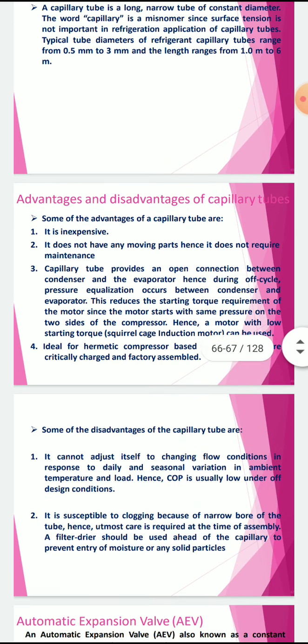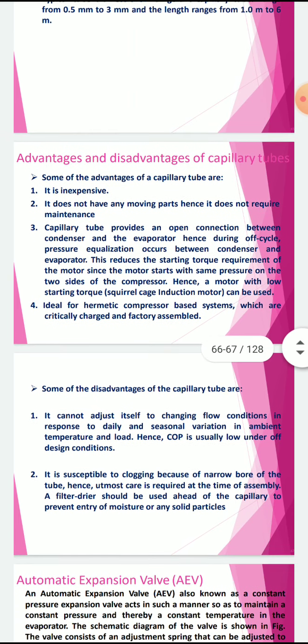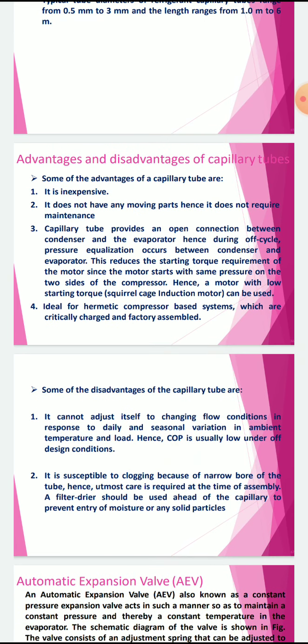Advantages and disadvantages of capillary tube. Some of the advantages of capillary tube are: first one, it is inexpensive. It does not have any moving parts, hence it does not require maintenance. Capillary tube provides an open connection between condenser and the evaporator.